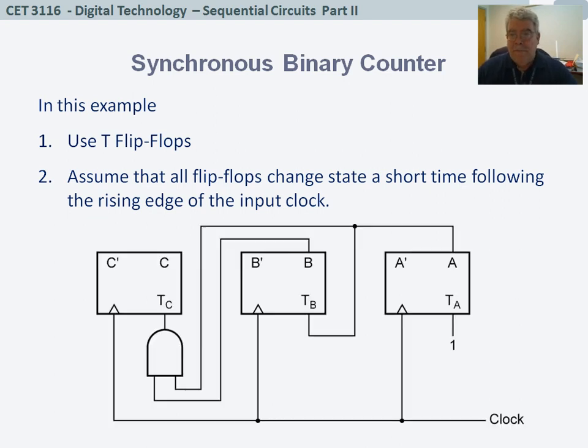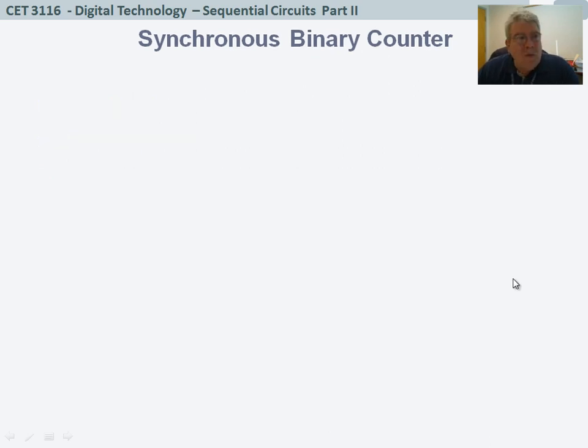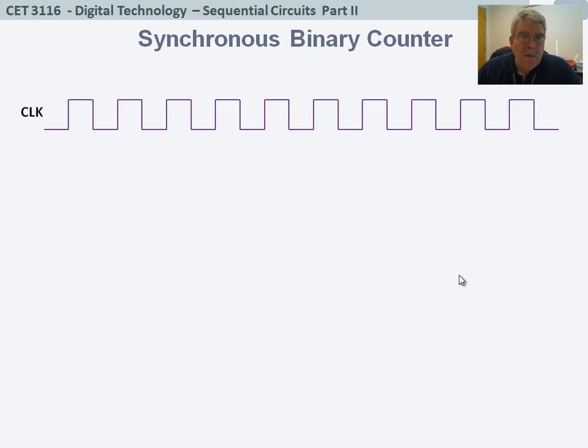And here's the circuit that we just designed. It is the counter that we have already seen, but now we followed a procedure step by step that brought us to this design. The way we can prove that this works is with a waveform. Remember, this is our clock. In this case, we're using rising edge flip-flops. You could use falling edge, that doesn't matter. The change of the clock will be determined in different ways.